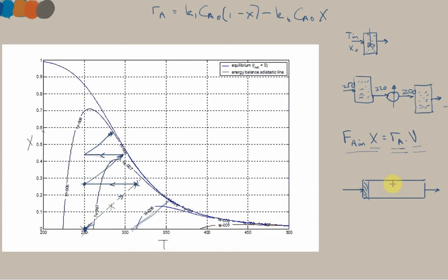And then if we consider points near the middle, we'll get some other values and so on. So we will be able to observe all these intermediate concentrations across the plug flow reactor. We'll observe the intermediate temperatures also. So all these are observable in the plug flow reactor, and they are not observable in the CSTR.